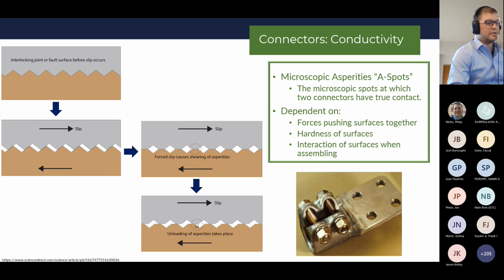But over time, what you'll notice is small amplitudes of movement from changes in temperature and vibrations at 60 hertz. Vibrations will start to occur. And then you'll notice those peaks are going to start to get sheared. That's where your uniform roughness and your asperities are not going to line up as they were prior. So then you'll start to see these gaps, and that affects the resistivity of your connectors and the conductivity that is allowed.